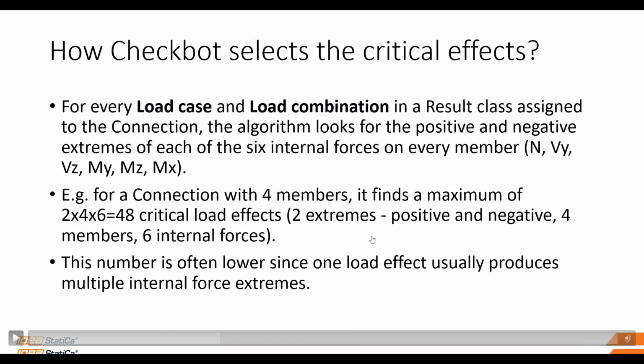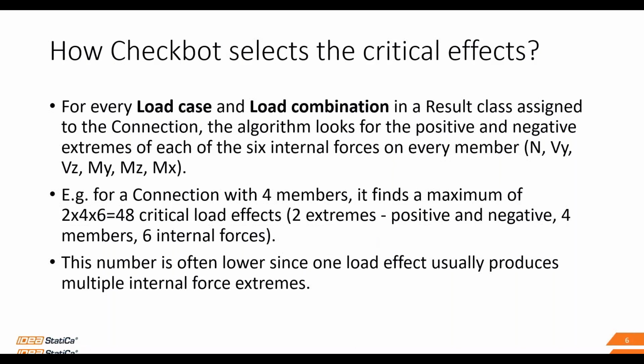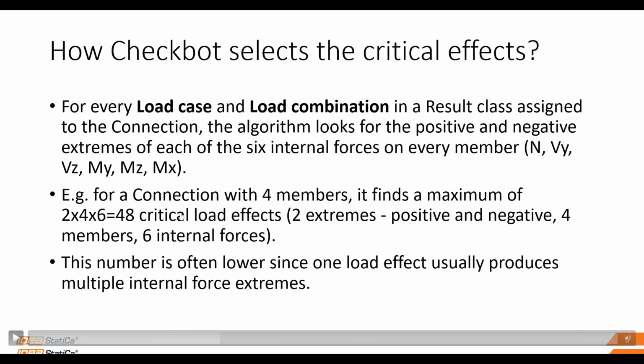So that's how we select the critical values. Of course, this number is often lower since one load case will be critical for 2 members or 4 members or 3 members. So that value of load cases selected will decrease a little bit. So that's how we select these critical effects, all right? Of course, you are always able to select which load combinations you want to use, and you unselect the critical effects option, all right?